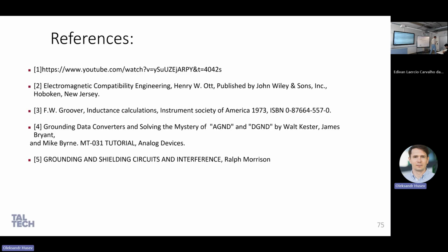But what I said, in each particular case, you have your ideal circuit in simulation. Just for example, you have PSIM or another simulation tool where you put your ideal circuit. But then you obviously understand that by your design you add parasitic capacitance or inductance, right? Always ask yourself what will be worse. A very good example is if you have a so-called switching cell with a half bridge converter, and here you have inductance.